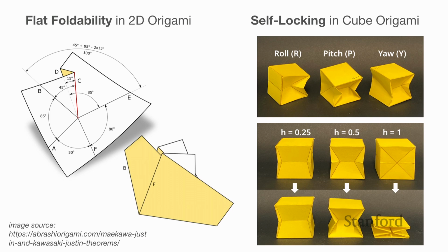But that's actually a very interesting property when it comes to robotics, because we might sometimes want a self-locking property. Let's say we want it to self-lock into a roll, pitch, or yaw configuration. That's actually quite great for designing, without having your motor be like, oh, I have to actuate and hold this position if that's the final end state.